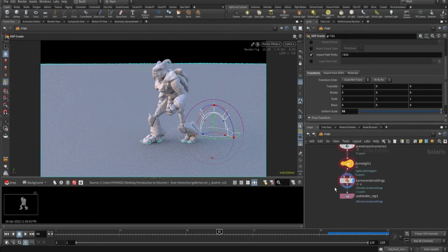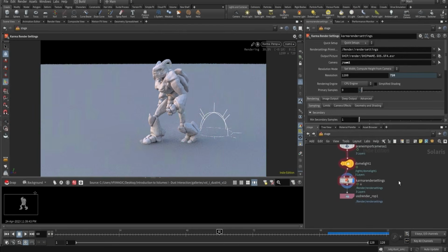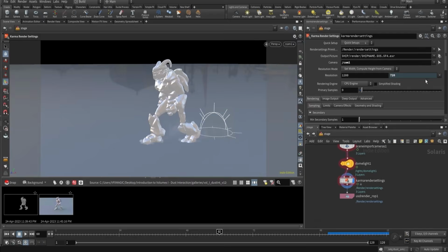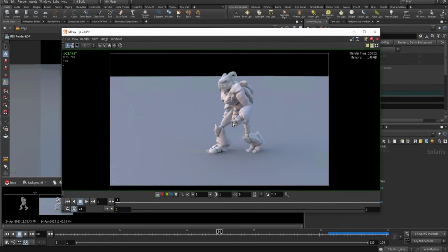At the moment it's using CPU, and let me just snap this out. I want to check rendering speed as well, so let me just turn this off. Let's use full HD only. Cool, let's just render to ambient. Yeah, smoke is not visible, but we will work on the shading later. But at the moment it's taking 52 seconds to render this, and I have other options as well.